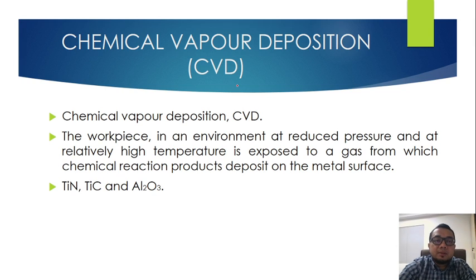And then the second one is CVD, chemical vapor deposition. The workpiece, in an environment at reduced pressure and at relatively high temperature, is exposed to a gas from which chemical reaction products deposit on the metal surface: TiN, TiC, and also alumina.